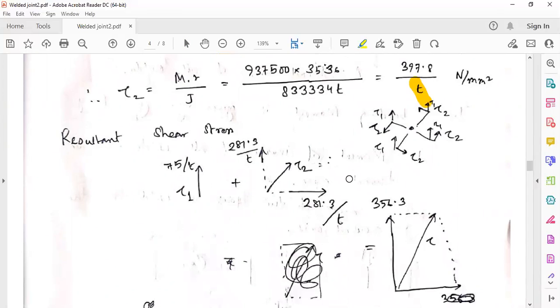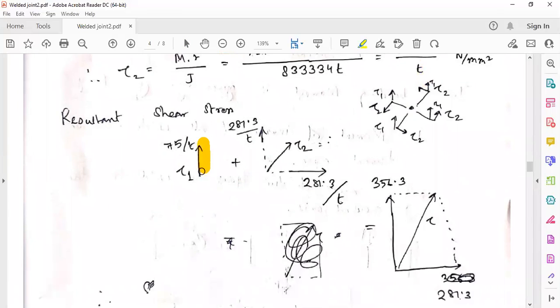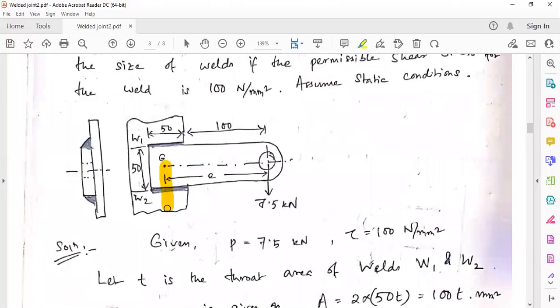Now, this is another part to understand. Here you see this is the upward shear stress. Look at this: this is the upward shear stress first of all, and each farthest point of the weld has to provide an opposite moment. This farthest point will provide like this, just the way we have seen in your threaded part.